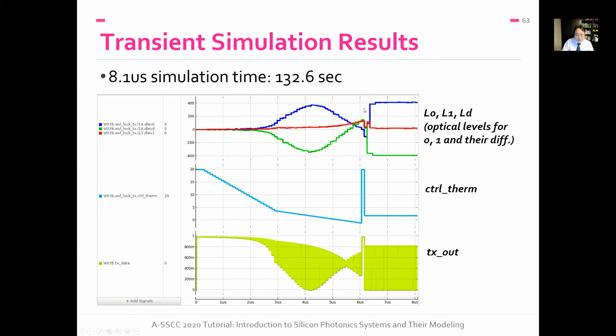So this simulation includes an extremely high frequency optical signal propagating through the ring resonator, the models for the analog circuits doing the A to D conversion, as well as the D to A conversion when you are driving the heater, as well as driving the ring resonator.